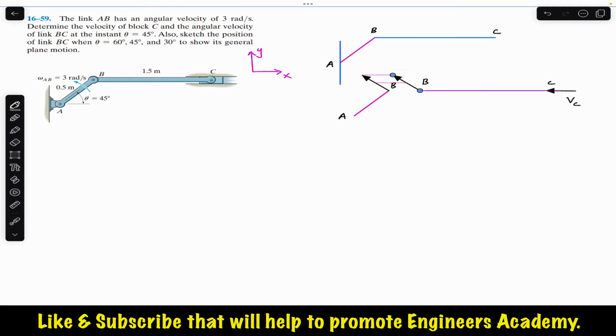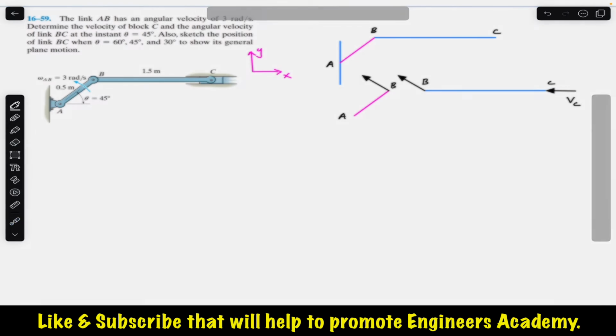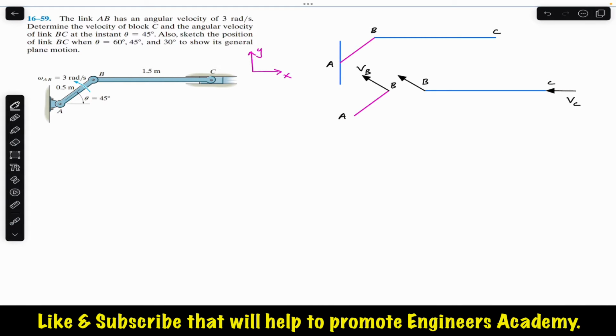So at point B, this velocity VB is perpendicular to this AB arm, and similarly we will have that same VB here as well. So here this is VB and this is VB. This link AB is making a 45 degree angle here.